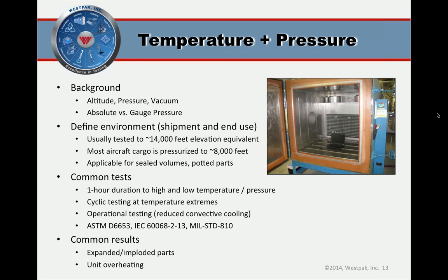It's also interesting that variations on this theme include things like vibration plus pressure and temperature. This has become what we consider to be a pseudo-standard for products such as, believe it or not, ice cream. Ice cream is a whole series of closed cells. You ship that to higher altitudes, inside the cell wants to blow up, it wants to expand. And that means the ice cream is going to expand right out of its container. And by George, if you look at ice cream in ski altitude areas, that's what you'll see is blown up ice cream. And it affects the flavor too.